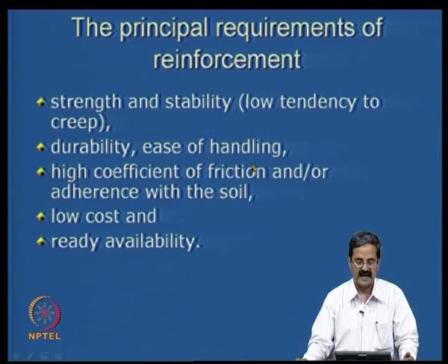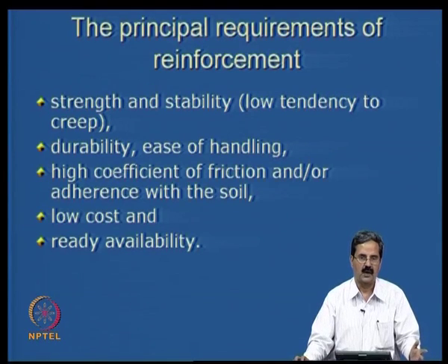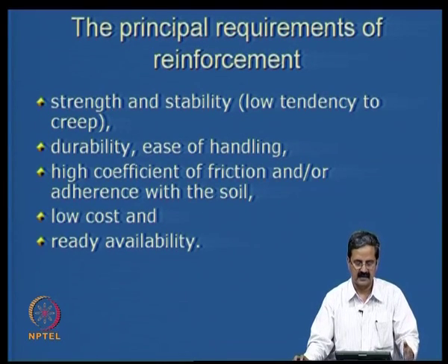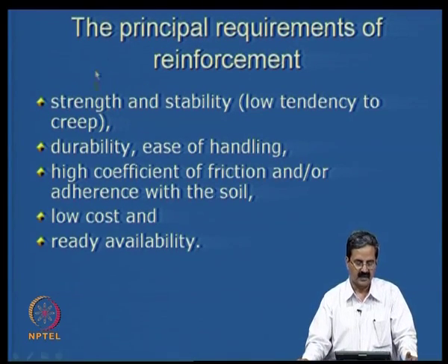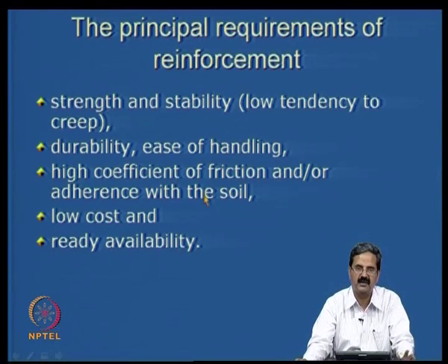Then ease of handling: you should be able to handle the reinforcement in a very easy manner, like you can bring it in a lorry or in some sort of containers and put it on the field. Very importantly, a high coefficient of friction or adherence with the soil, like we need good friction between the soil and reinforcement. That's very important, because that's the whole concept of reinforced soil. Now, it should have low cost also.